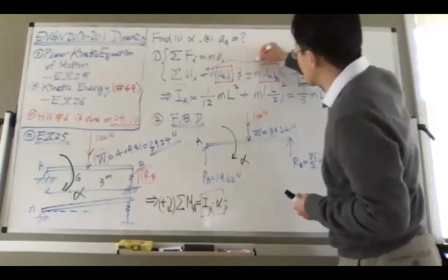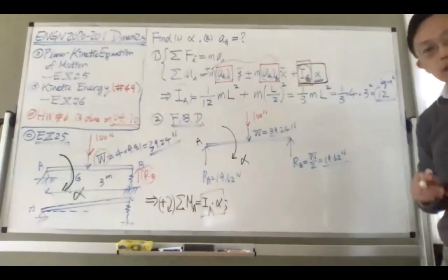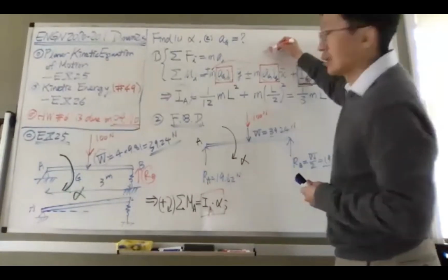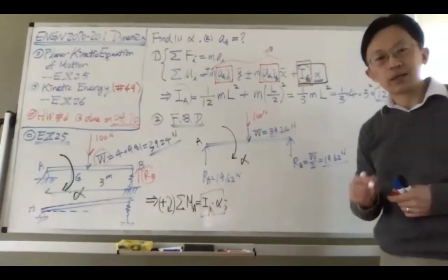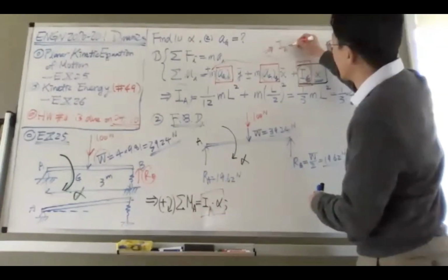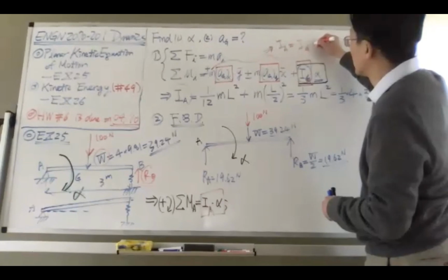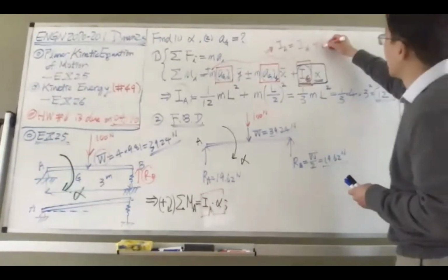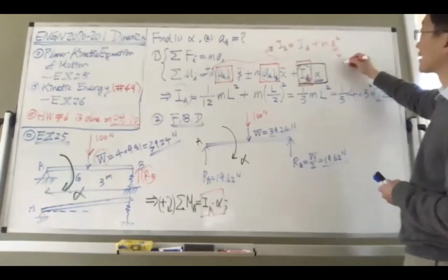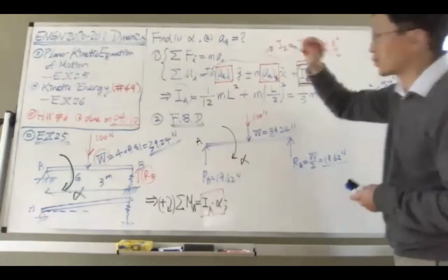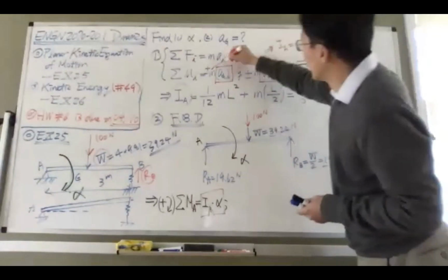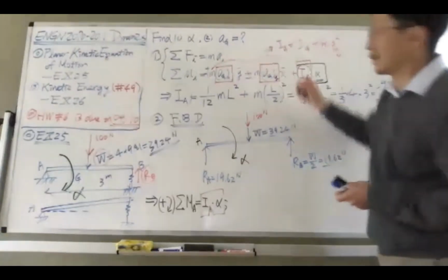Therefore, this result is actually a derived result when you use it. This is just like what we said before, the parallel axis theorem. The mass moment of inertia at the center of rotation equals the mass moment of inertia at the center of gravity plus m times d squared. And this d here is nothing but the product of these two. So the second term here already accounts for the first two.